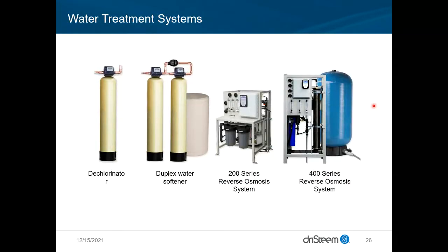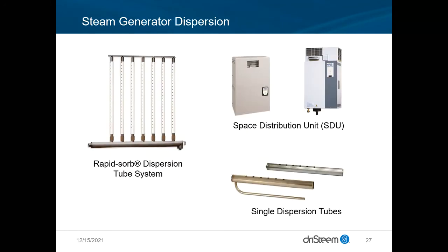Also, remember that we want to make sure that we keep water treatment systems in mind. That greatly affects maintenance. You could have anything from as simple as a softener all the way up through RO. There's potentially even DI systems available out there too, but just know that the effort put into cleaning the water and keeping it mineral free does pay dividends back on the maintenance end of it. So all these membranes and filters are a lot easier to replace than it is to descale a humidifier tank. So keep that in mind when you're selecting systems as well.